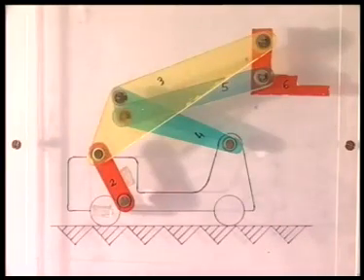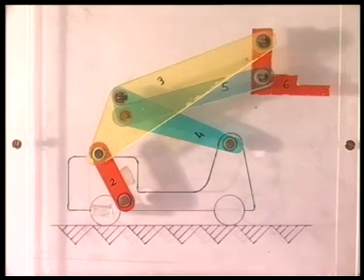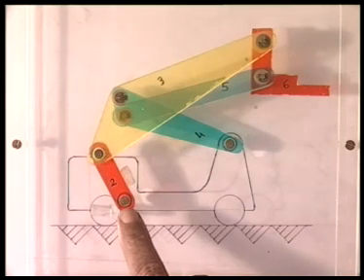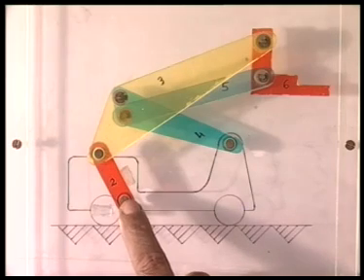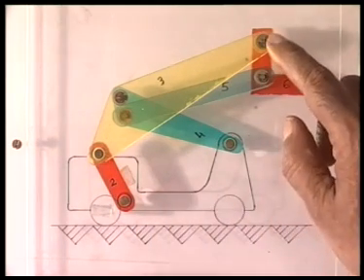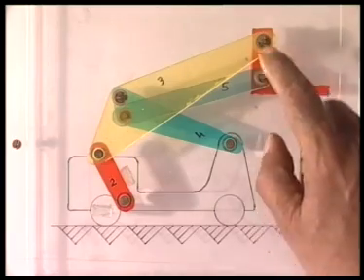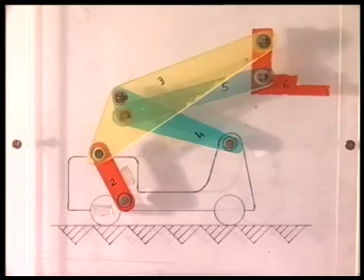Let me now summarize this multi-stage synthesis of this guideless forklifter as we have completed in today's lecture. We have chosen first O2. This is this fixed pivot at a convenient location of the body of the truck. We have also chosen a vertical line in front of the truck which is convenient for the movement of the fork.